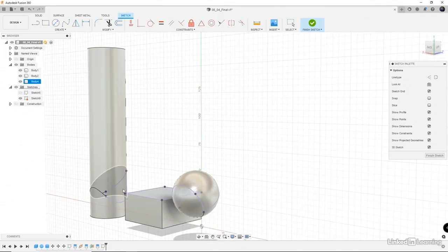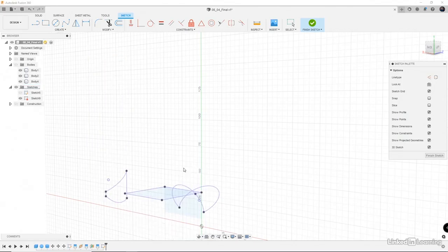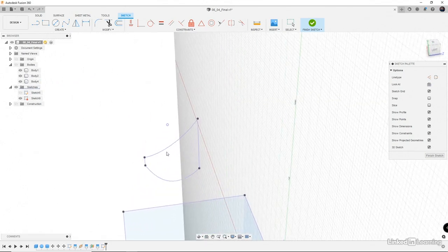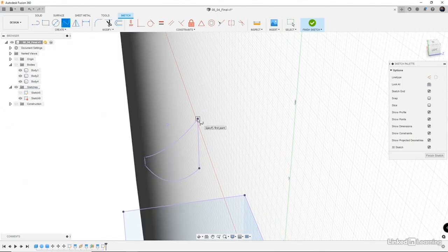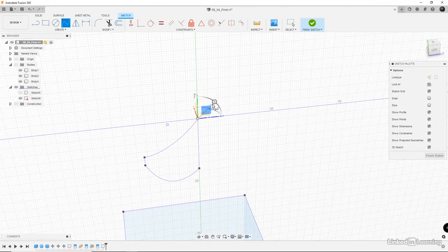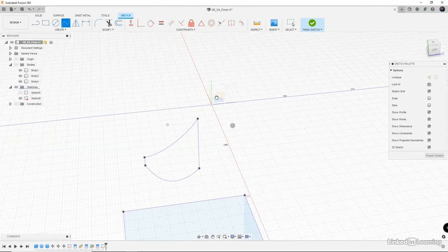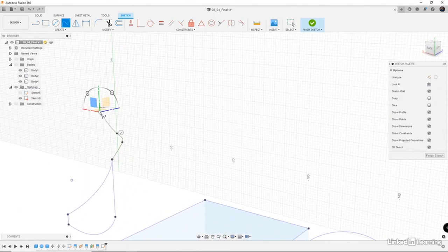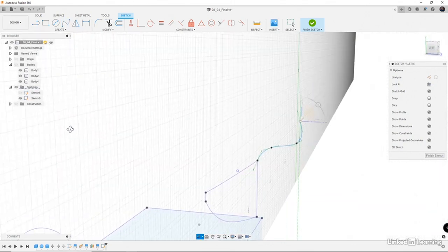You can bring in this geometry, but you already have this geometry. Where this becomes really powerful and useful is in the case that I had a really complicated mold line, and I needed to modify the line on the mold. So what I did is I used this tool here to bring in that 3D surface. And then I came up and I used a fit point spline, and I selected the end, and I used some 3D sketching tools, and I built some cool geometry, and I basically built the surface that I need. And so you can build out whatever extension of that surface that you need.